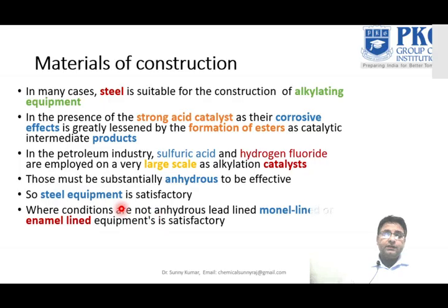Where the conditions are not anhydrous, lead-lined, monel-lined or enamel-lined equipment is satisfactory. Actually, we generally coat a layer of a monel-based or enamel-based material on these equipments.